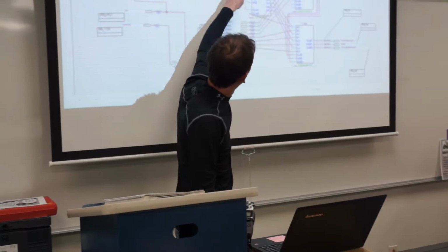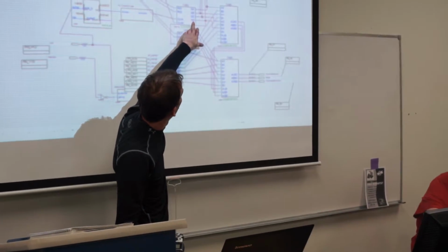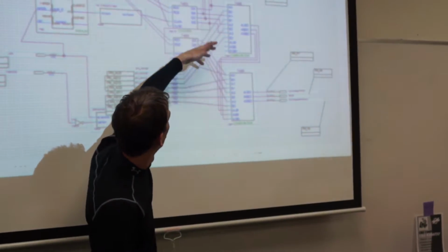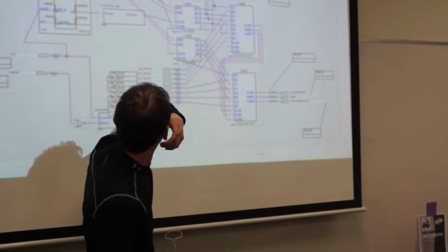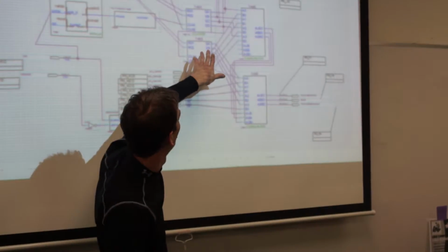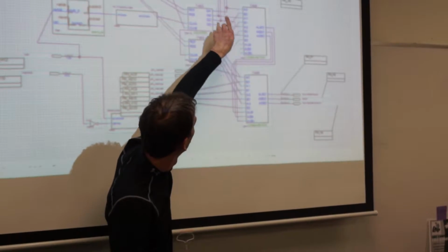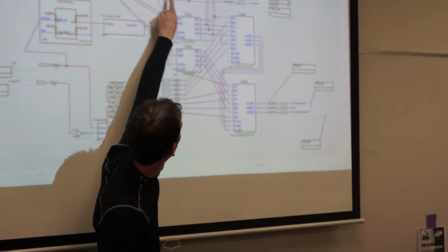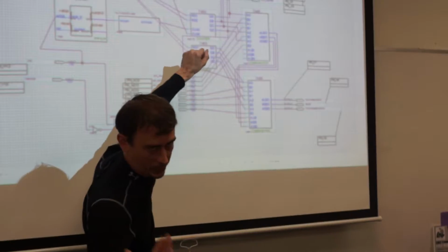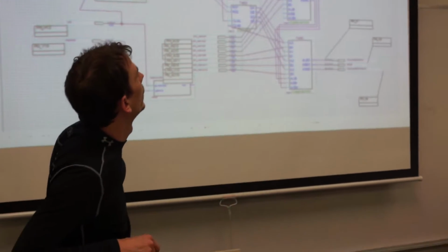These counters work. The output of our highest bit here feeds the clock into this. So this becomes our 8-bit counter. These actually have another feature, so to make them just a binary counter, you have to tie the A output, the least significant bit output, into what they call the B clock input, and that makes it count just as a normal binary counter.